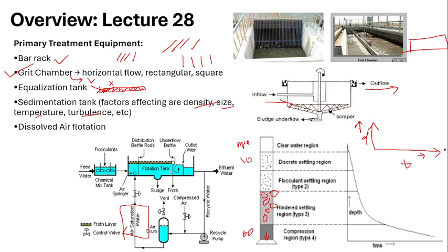Here in this flotation tank, the water is here, baffle rods are here. So this water is completely mixed by using the baffles here. And with the interaction of this air sparger, the air molecules will allow the water constantly to be mixed. And then what happens? The sludge is collected down and the pure water is flowing out as the effluent water. Here we are using saturated air as a medium for separation. So whatever air supplied here will help in the decomposition of the organic matter in this flotation tank itself. That is how the sludge is formed.